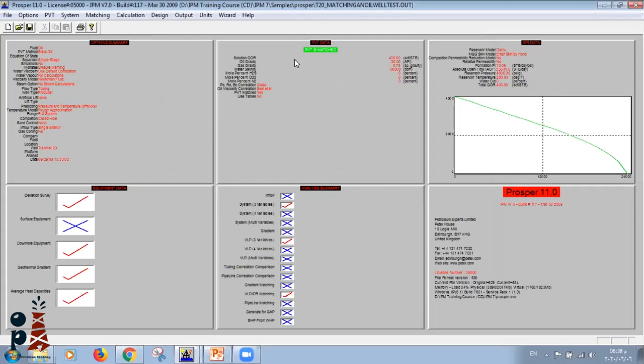Here is the PVT section. We mentioned before that it's very important for us to define precisely, or accurately, the fluid down there, because it's a main factor to calculate the pressure drop across the reservoir and also across the wellbore.